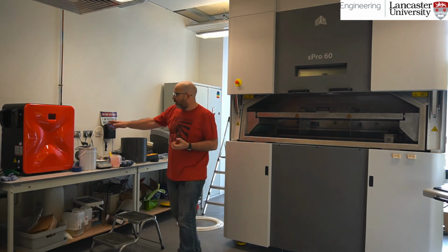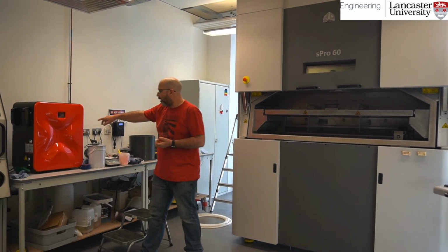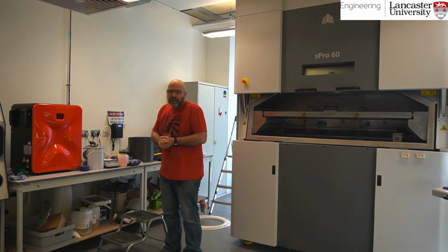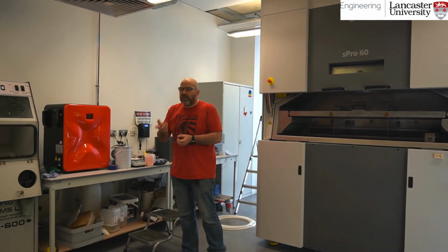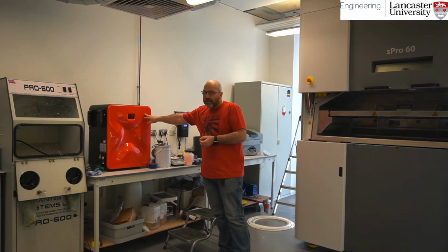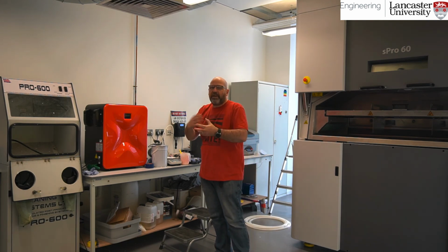And this exactly the same process, but on a smaller scale, is the Lisa by a company called Sinterit. We're in the process of getting 2 of the latest iterations of the Lisas. Does the same job as that, but because it's smaller, it's easier to turn the machine around, to reprocess the powders, to sieve them and everything else, unload the machine, but obviously not as big a build volume, not as powerful a laser.